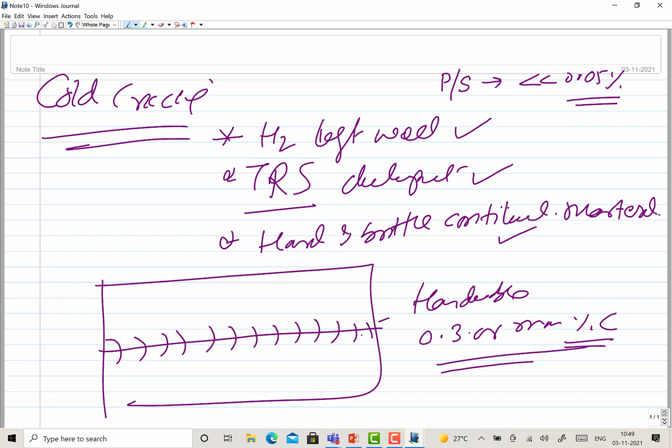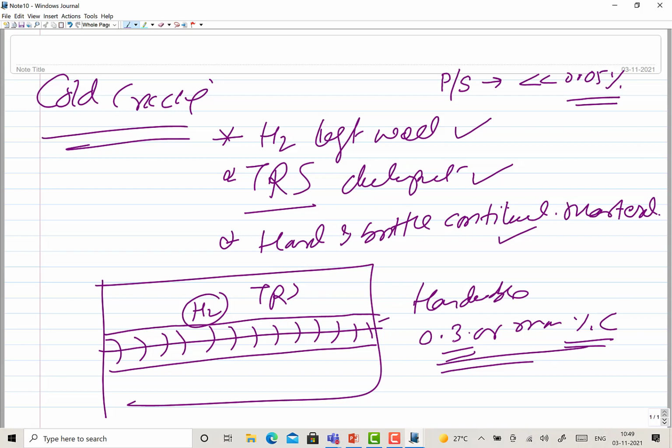due to the presence of moisture, there is always some amount of hydrogen, and due to the differential heating and cooling, there is always some kind of tensile residual stress. And when it is coupled with high carbon content or high carbon equivalent, like CE greater than 0.3, you will find that there is some amount of martensite formation in the weld as well as the heat affected zone.